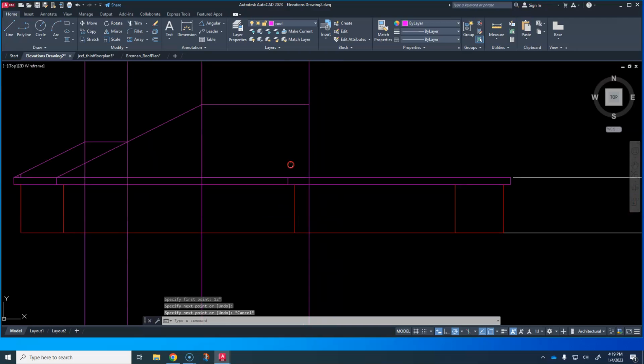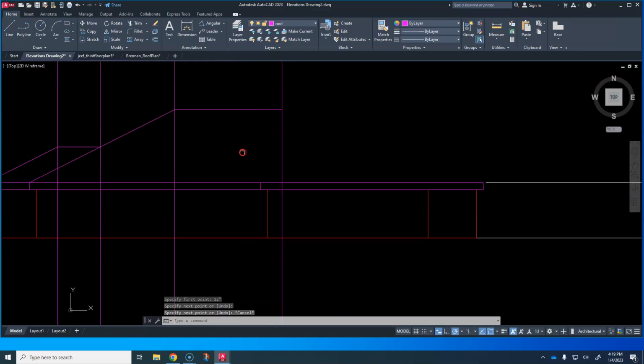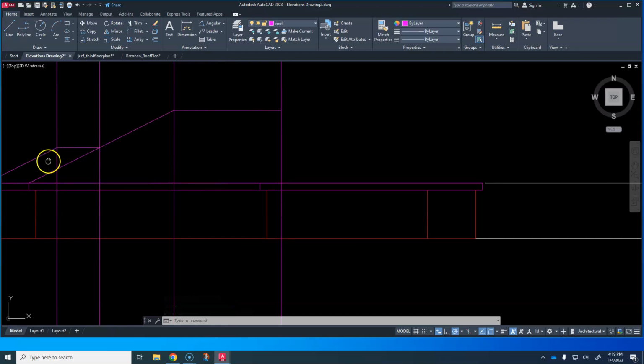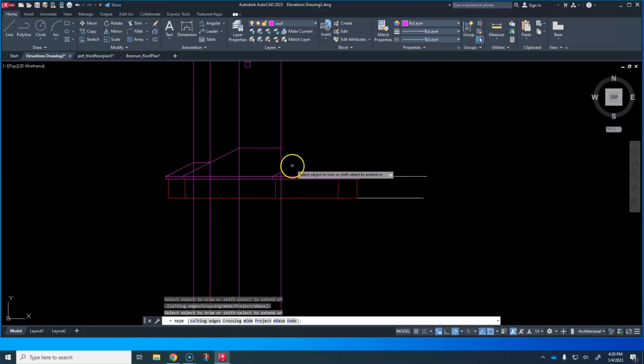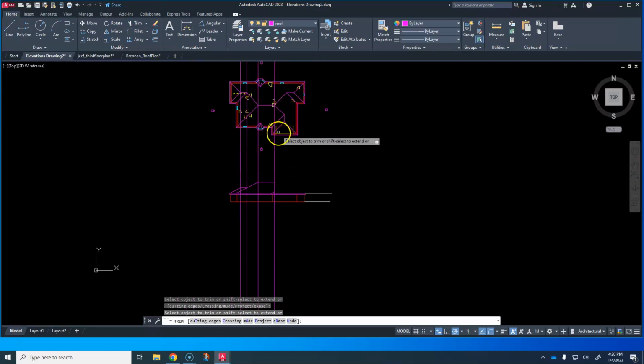Okay. And 27 degrees, or again, I can copy one of these angles over here. So I'm going to draw it and just kind of take it up to here at 27 degrees. In this case, make sure you hit it exactly right. You kind of got to draw it a little further and then tab over to the degree button and type 27 and then enter. And then you got to come back and trim that little tail off right there. Well, actually, I didn't have to do that because I need to draw it a little bit further.